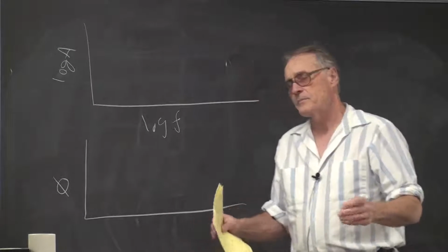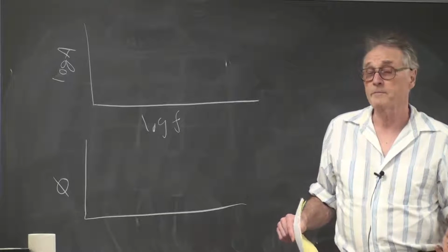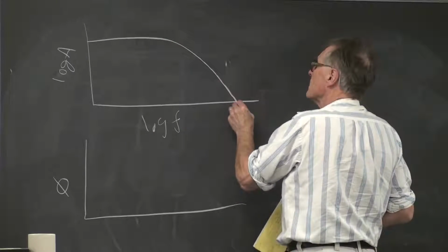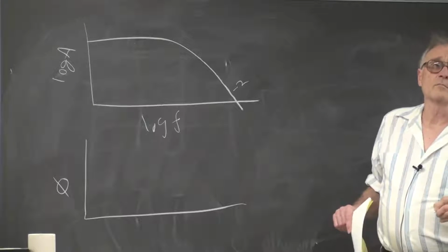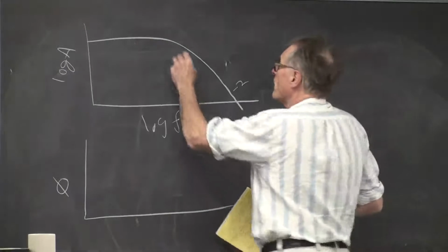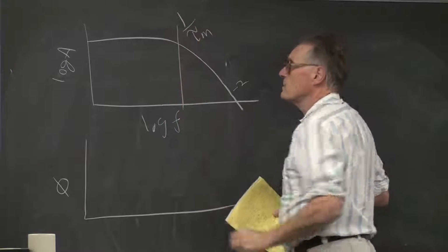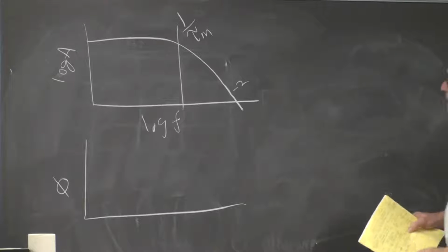And I'm going to motivate this by saying we're going to solve the equation for a motor in just a minute. But what we're going to find is that a motor has a Bode plot that looks like this. And the asymptotic slope is -2 on a log-log plot, with some time constant 1 over Tm, where Tm is the time constant of the motor, which you would get by spinning this baby and watching it decay in time. Right. So you'd determine the time constant experimentally.